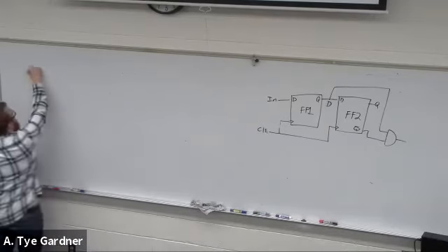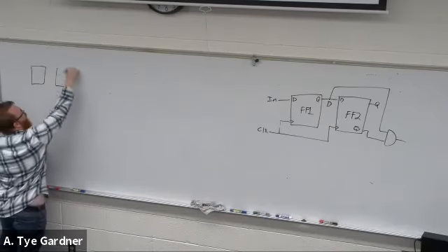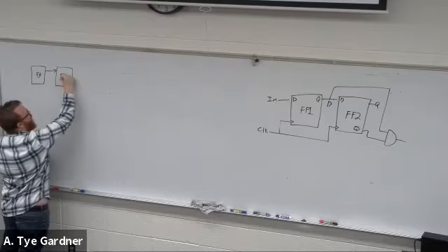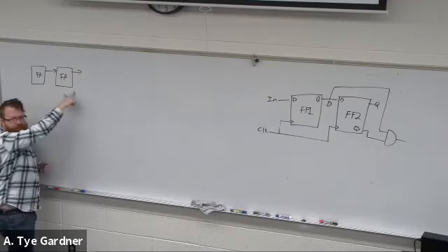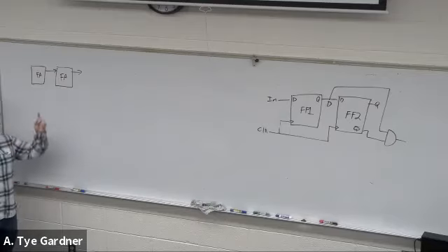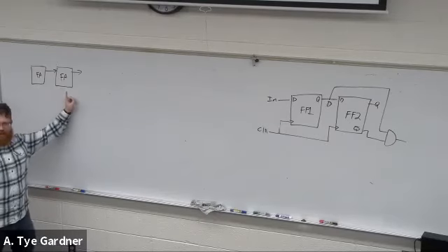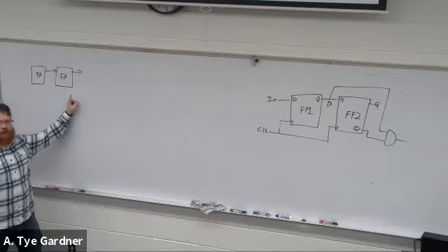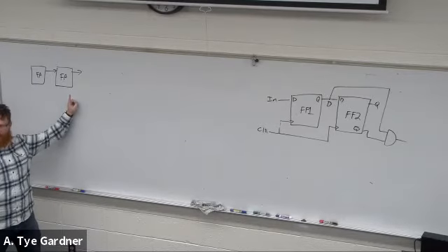So a ripple carry adder is where I take a series of full adders and I just start stringing them together, right? What's the problem with this type of adder? The delay is each bit that I add adds a propagation delay of at least 3 gates, right? If you think about your logic, the optimum size of a full adder takes 3 gates. You can build it with 2 gate delays,